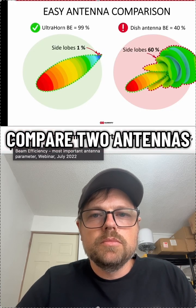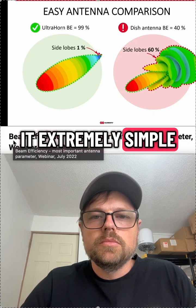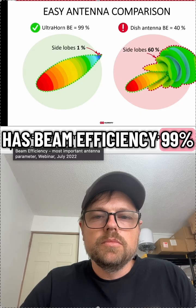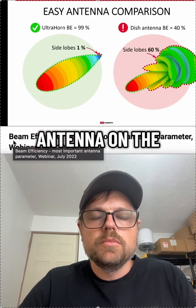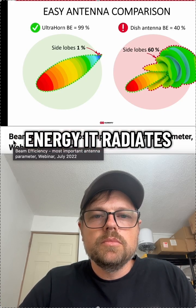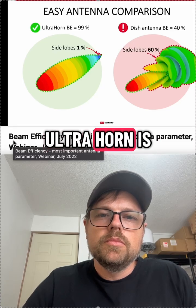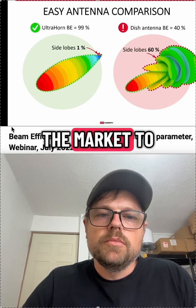If you want to compare two antennas in terms of side lobe performance, beam efficiency makes it extremely simple. The higher number wins. In this example, the ultrahorn on the left has beam efficiency 99%, so only 1% short of perfection. A generic dish antenna, on the other hand, has beam efficiency 40%, so the remaining 60% of the energy it radiates is in the side lobes. 99% is clearly more than 40%, and that's why ultrahorn is way better antenna in terms of noise suppression. In our opinion, the best on the market, to be honest.